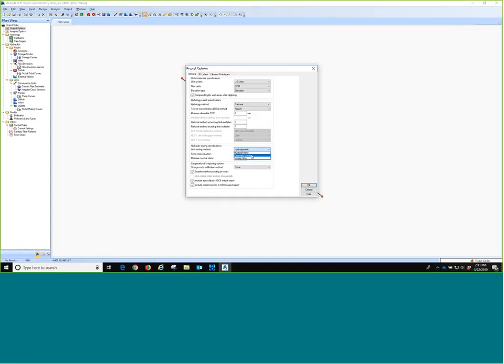So it's actually kind of nice, as an aside, when I'm going through my network, even if I'm going to include a force main, sometimes I begin by, after sketching out my network, if I want to make sure I didn't accidentally put any reverse slope pipes in, I'll run the model as kinematic wave. If it fails, it'll show me exactly where it failed. I can change my slopes, fix my inverts, do whatever I need to, and then when I rerun it, as long as it completes, I can then, on the fly, change my method to hydrodynamic, and away I go.